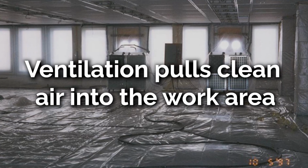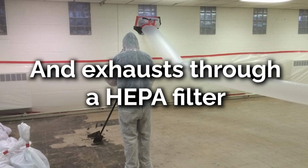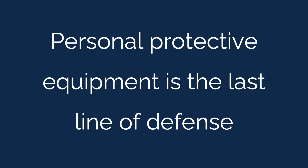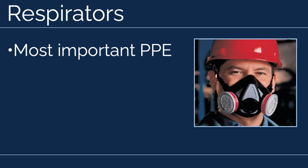Ventilation pulls clean, uncontaminated air into a work environment and always exhausts contaminated air from the work area through a HEPA filter. This reduces the concentration of airborne asbestos in the work area and reduces workers' exposure. Personal protective equipment is the last line of defense against asbestos exposure. Depending on the job, OSHA might require head, hand, foot, and whole body clothing. A respirator is the most important PPE.